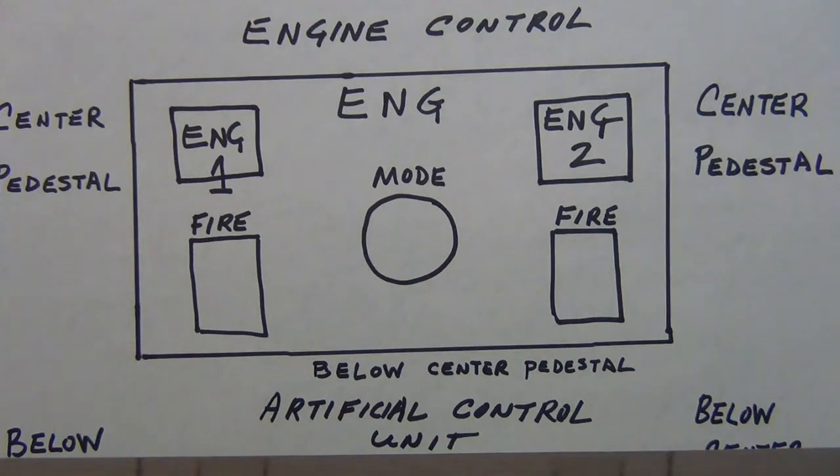You've got a 0, which is your neutral, and then you have your negative 20 degrees downward, so that's reverse throttle. And you've got up to your 45-degree TLA, your thrust lever angle. Again, you don't have to be memorizing 45 degrees or negative 20. Just be aware that you've got 6 detents or positions in which the thrust can be placed.